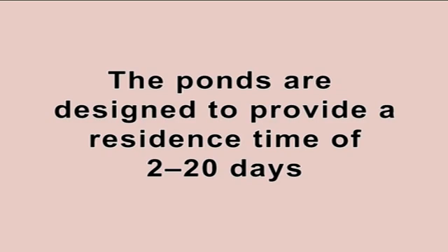The ponds are designed to provide a residence time of 2 to 20 days with surface loading of 5.5 to 22 gram BOD per day per square meter.